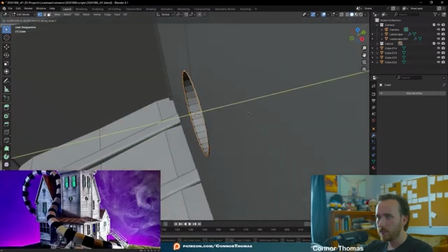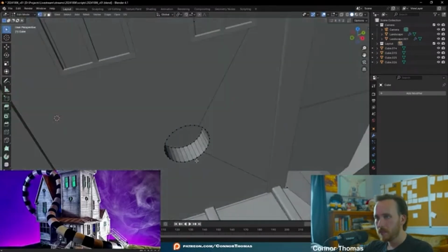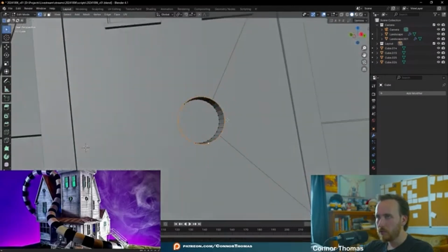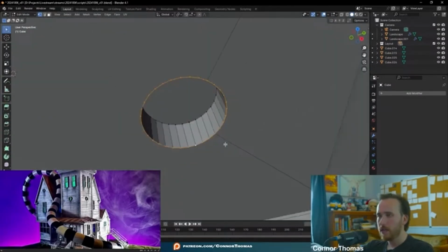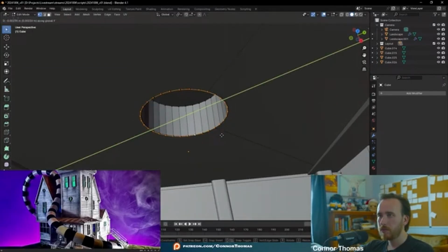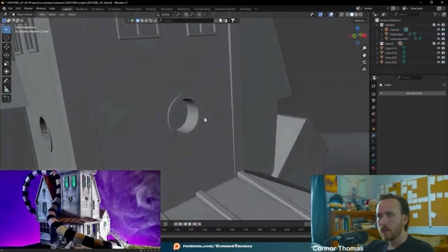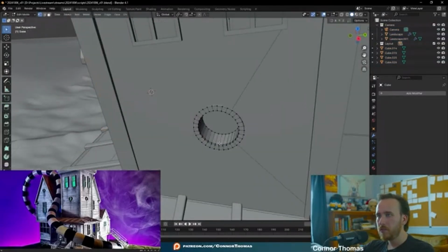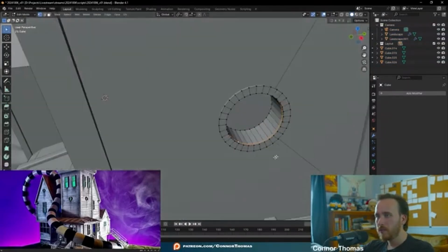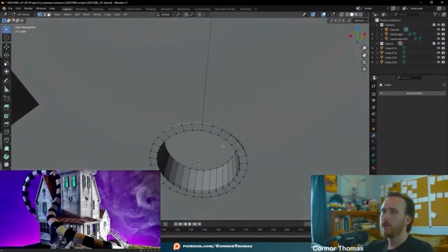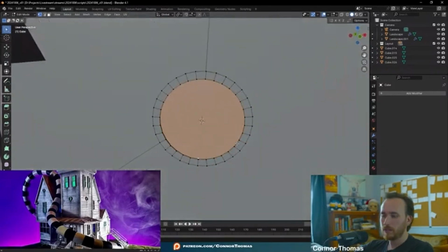little bit easier. And let's do the same thing for the other side. So select that side. Just go ahead and select these vertices as well. Duplicate them. And then extrude outwards, extrude in scale, and then extrude inwards. And there you go. The other thing we can do also is select all of our vertices that go all the way around, fill it, press Y, P, selection. That way we get ourselves a window again.